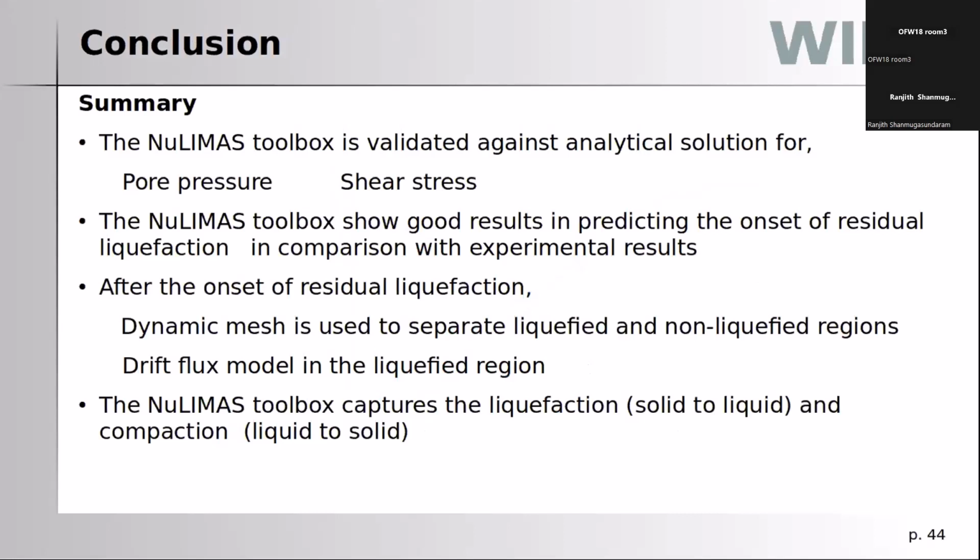Before that, I would like to conclude that with this numerical toolbox, we were validating the analytical solutions for pore pressure and the shear stress. You can see the toolbox shows very good results in predicting the onset of liquefaction. Also, after the liquefaction, we were using the dynamic mesh in order to have two different regions for liquefied and non-liquefied regions. After that, we were using the driftFlux model inside the liquefied region. And finally, this NULIMAS toolbox can capture the liquefaction, which is turning from soil to liquid, and finally the compaction from liquid to soil.